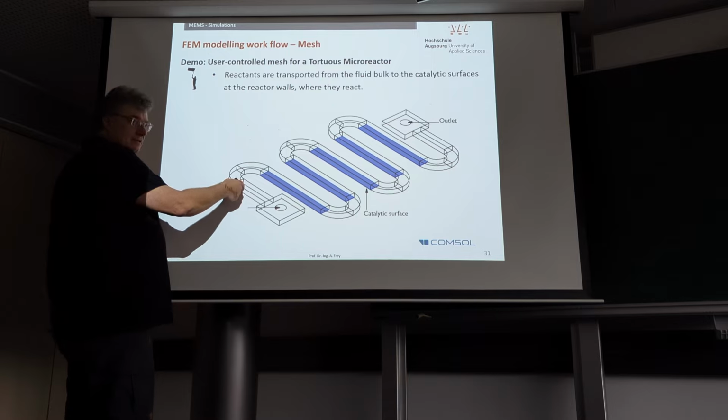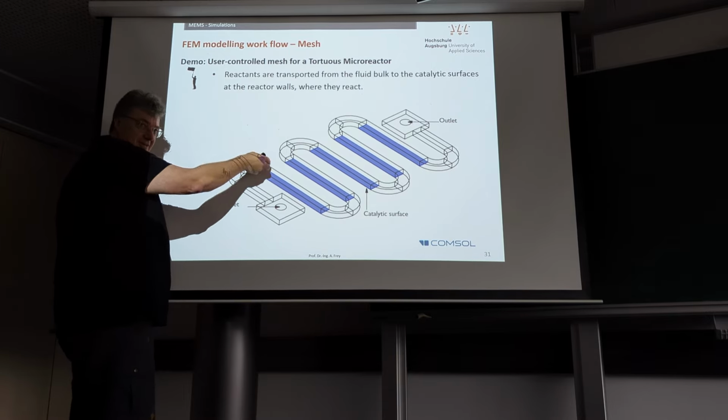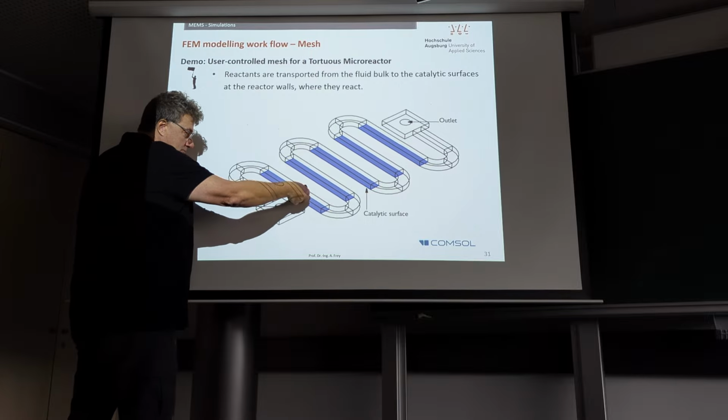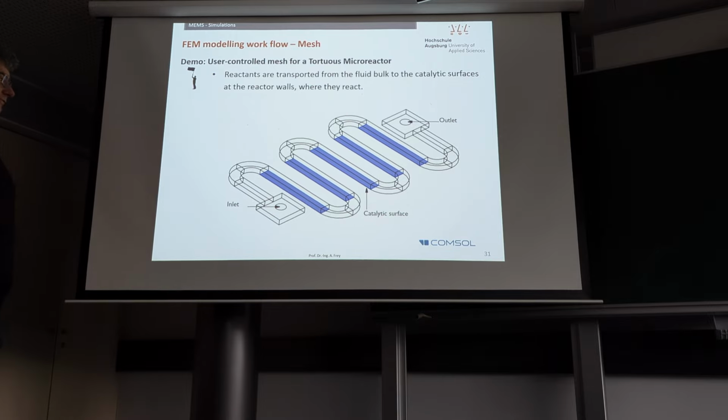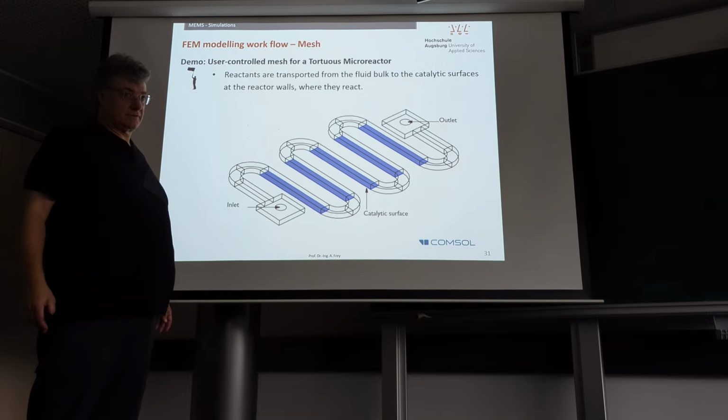It takes some distance. And then maybe if it's in the curvature, also something changes, but then it goes in that region. So we could have the idea in mind that the velocity does not need to be resolved along the transport in the meander in a very, very fine way. So we could use a more coarser mesh than we would get if we just use prisms.